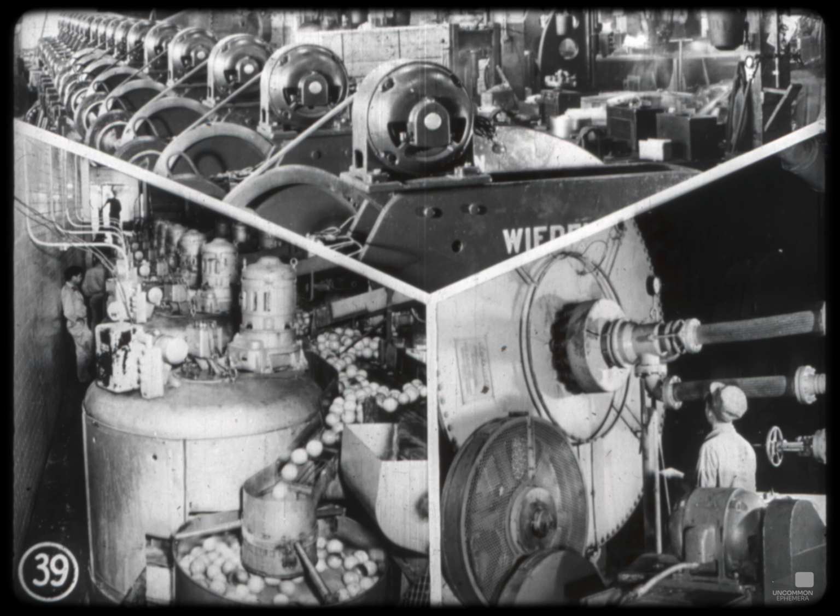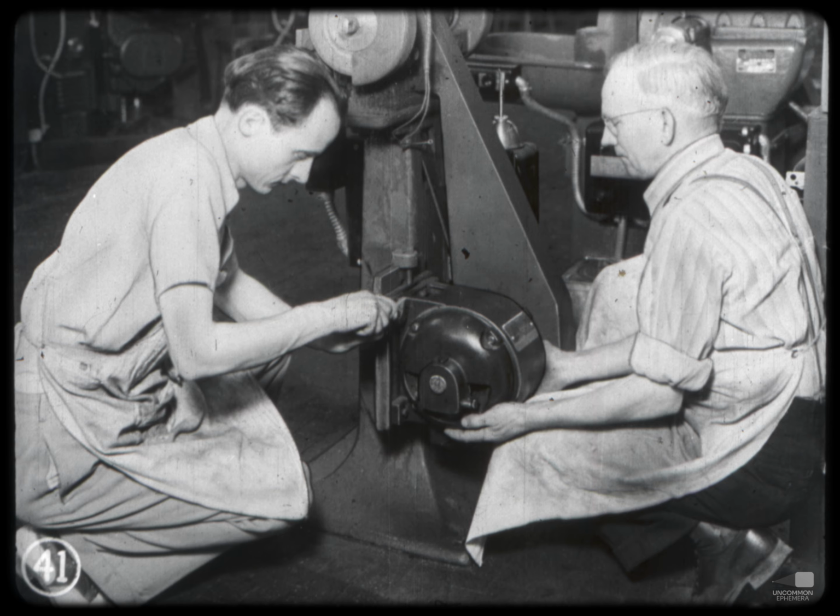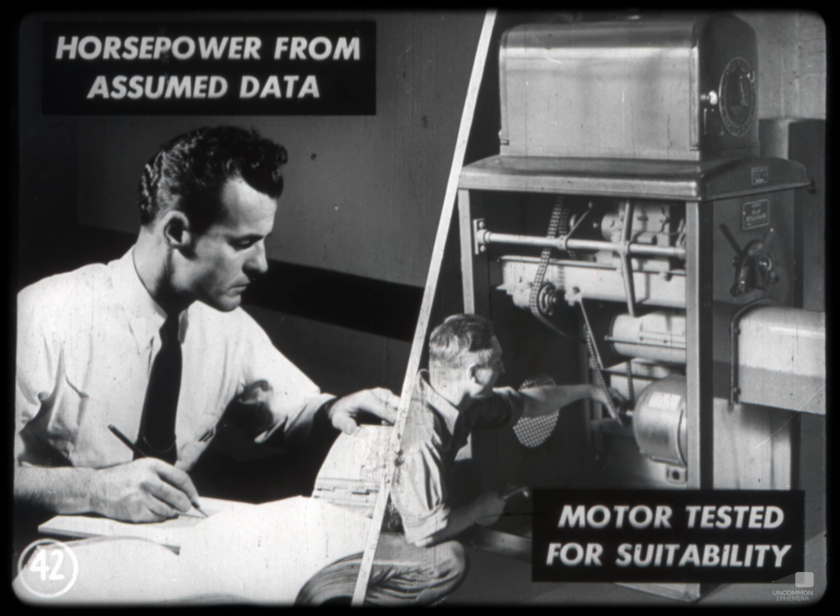Where the process is new or untried, often the motor horsepower must be determined by trial or testing. One method is to apply a motor somewhat oversized and then measure it under typical load conditions. At other times, the horsepower can be determined simply by comparing the new process with machines doing work of a similar nature. On some new process drives, the approximate horsepower may have to be calculated from assumed load data, such as friction and inertia, and then a trial motor tested on the machine for suitability.